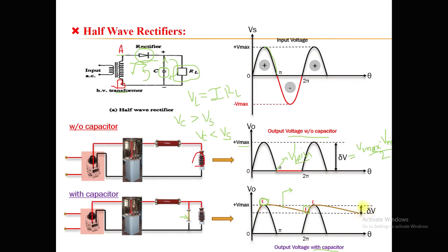So when we use this filter, the capacitor, at the output terminals of this rectifier circuit, we can achieve a value closer to our requirement. Elimination of the harmonics will provide us a very good result during the investigation.